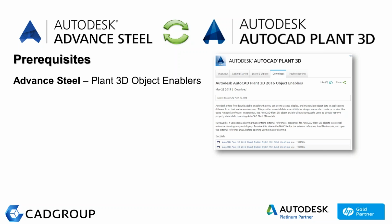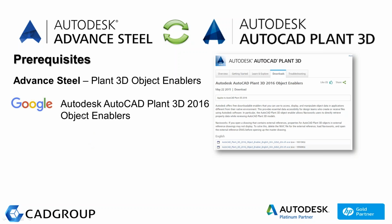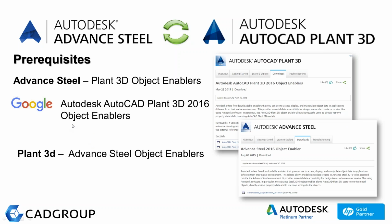So from Plant, Advanced Steel will need the object enabler for Plant, for some of the Plant elements. You're going to see bringing in information from different areas. So you can just Google the Plant 3D object enablers, guys. I can send you some more specific links later on if anyone needs that. Okay. On top of that, Plant 3D will need the Advanced Steel object enablers as well. So again, you can Google the Advanced Steel object enabler.